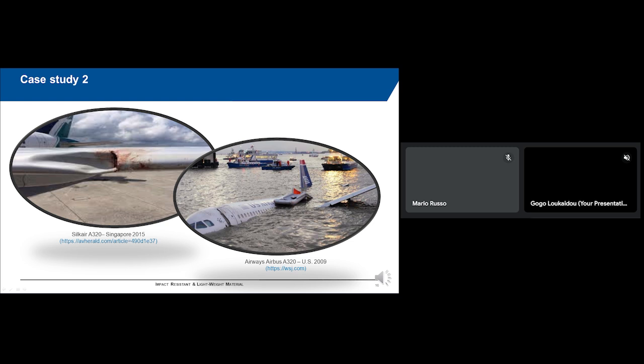To be fast, when you talk about impact, it's very important to understand the kinetic and internal energy of the material, and the sum of these energies is the total one. When the simulation is okay, you have the so-called hourglass energy, an energy related to the software, that is zero when the simulation is going on.